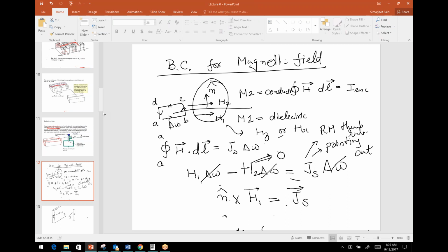So these analytical solutions are still pretty accurate, even though there is an approximation that the conductors have zero resistance. You can do full calculations by putting in conductance, and in fact, when you're doing research at high frequencies, especially anything above 10 gigahertz, with 60 gigahertz being a very interesting area of research these days, you don't do analytical solutions, you do numerical solutions.